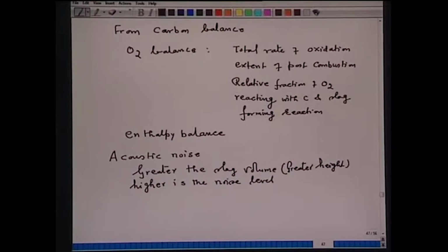So, by measuring the noise level, if the noise level is too high, that indicates that the height of the slag is very high in the vessel.